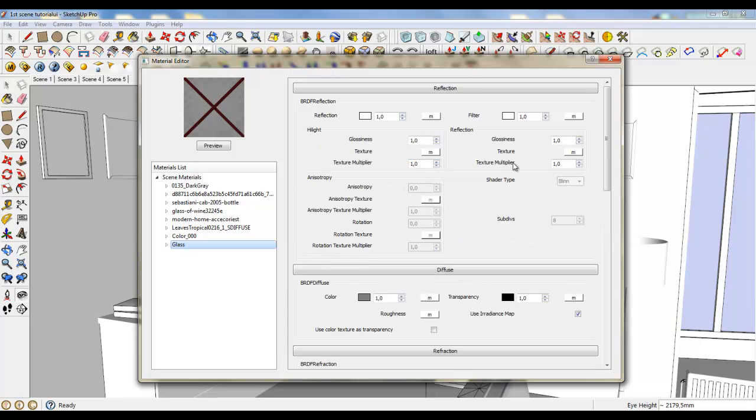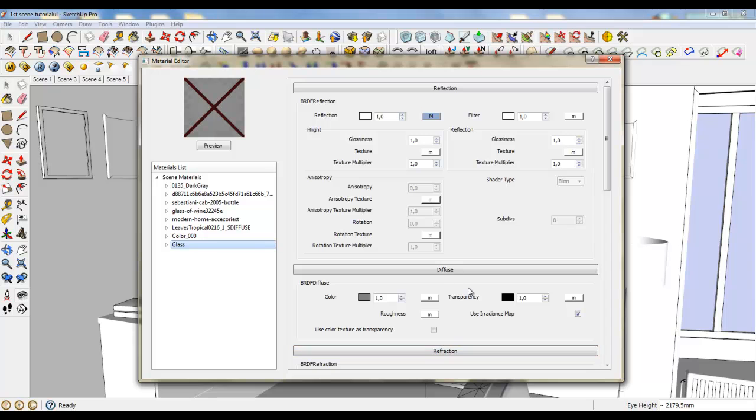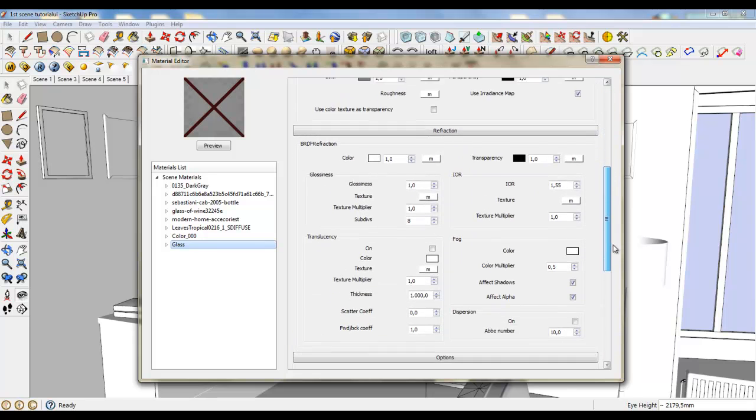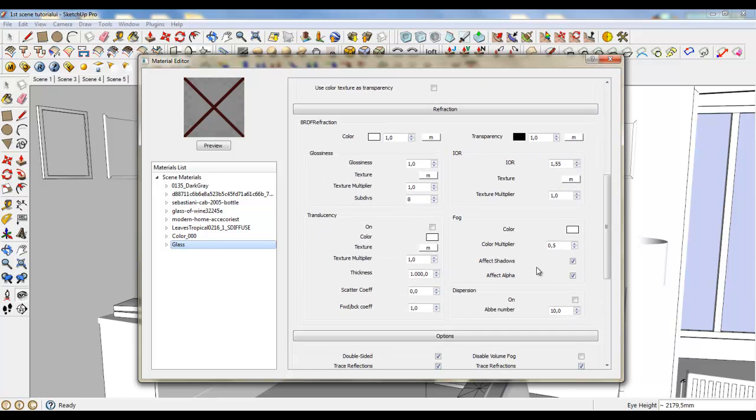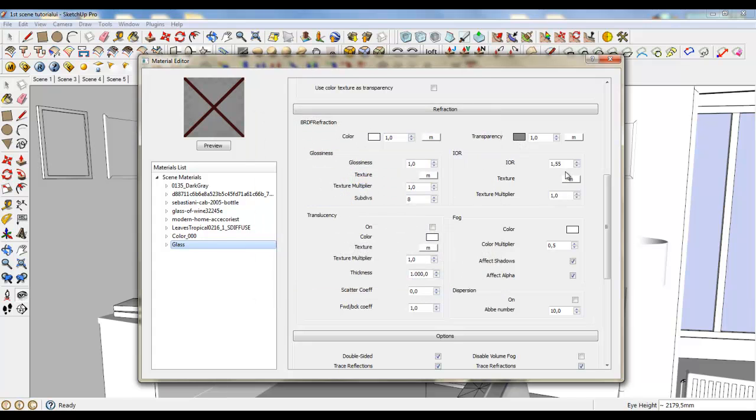Also we need some transparency, so we are going to have a refraction map and also a reflection map. So leave everything, just add a Fresnel map. Everything is okay. Now go to refraction and turn on translucency. Don't turn it on, just leave everything and make this something about the middle, and also 1.517, and we have a glass material.